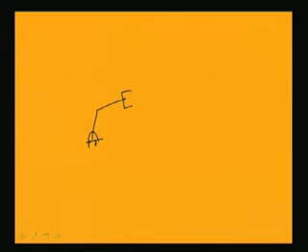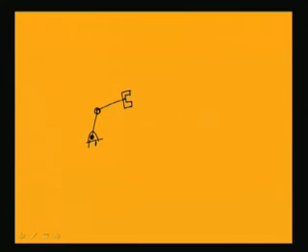This is the end effector of the robotic arm, and the joints are supplied with motors, which rotate these links. So, we are applying some torque or force to these joints. In a revolute type of robotic manipulator, you are supplying the torque, and in a Cartesian type of manipulator, we are giving the force.